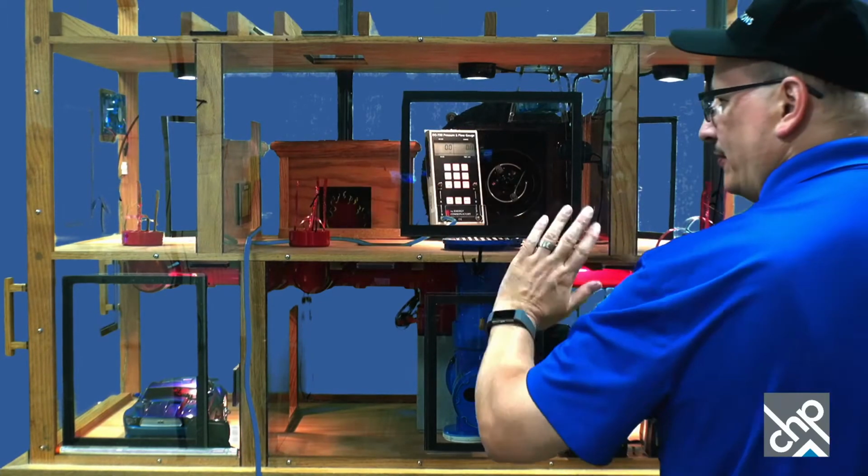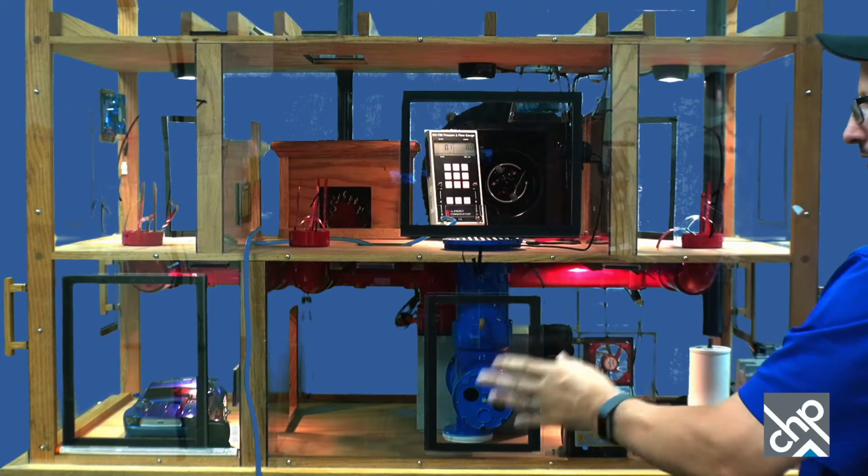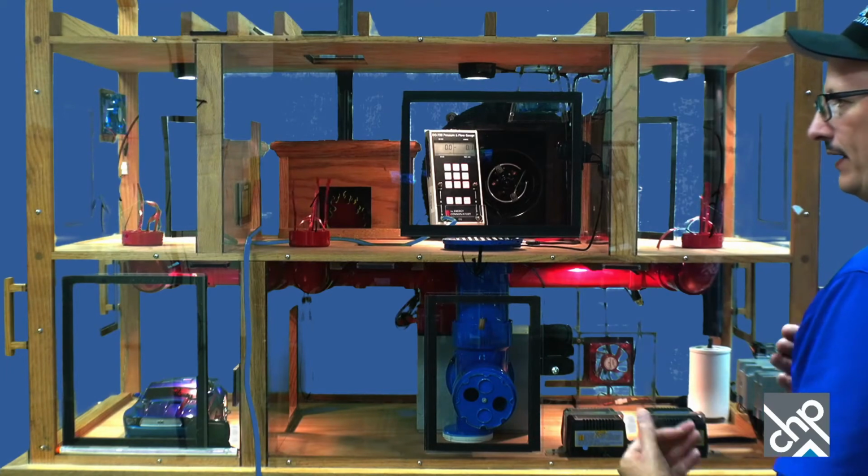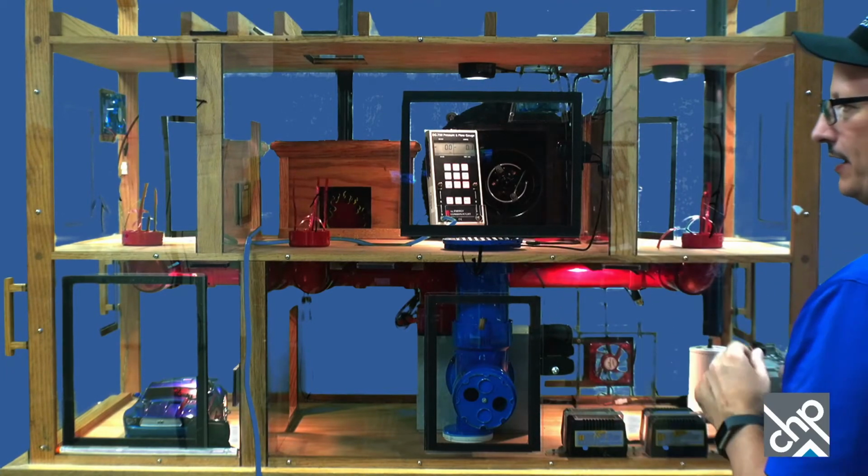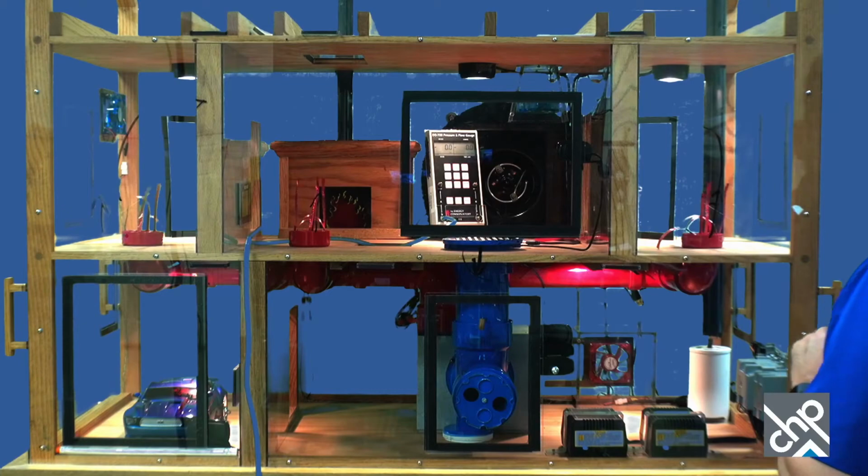Furnace fan is on. You can see that the streamers are on. No leaks, all that kind of stuff. And you can see the manometer reading in there. What we're reading is the number on the left, and that's the one in the living room there. And basically, the air handler's on. There's no pressure difference at this point. But then we're going to start closing the doors.